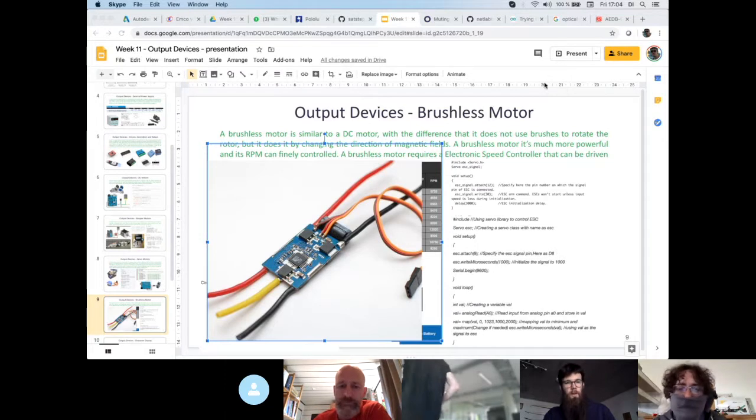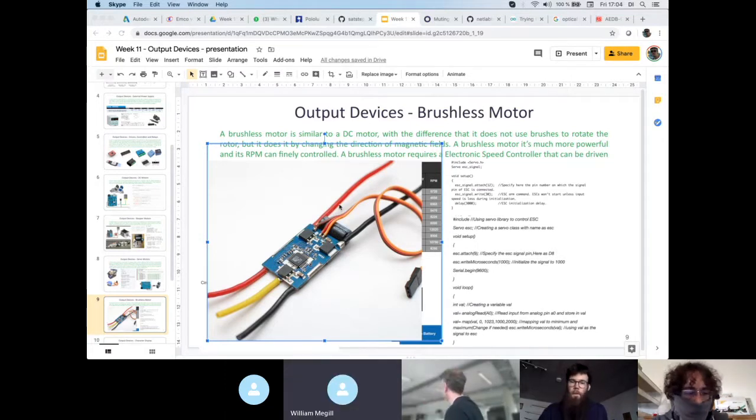Okay. Thanks. This comes back to another topic: different brushless motors are made for different purposes. Like the ones that are made for the drones, guys, are not really good to have a lot of torque since the start of the motor. So we might need to look to a specifically made brushless motor.